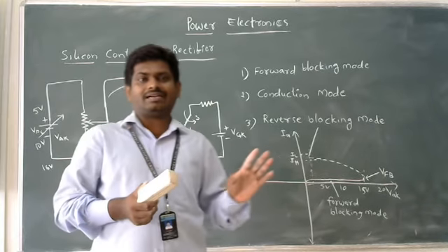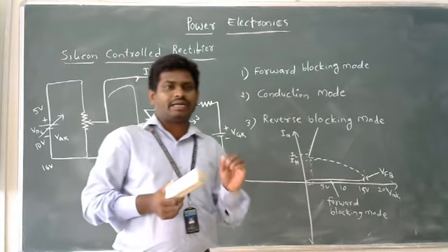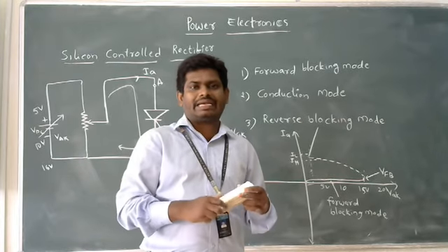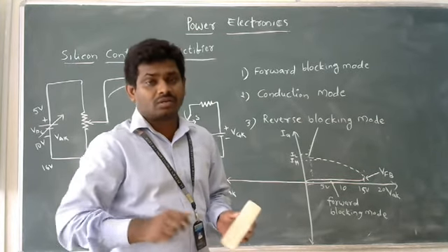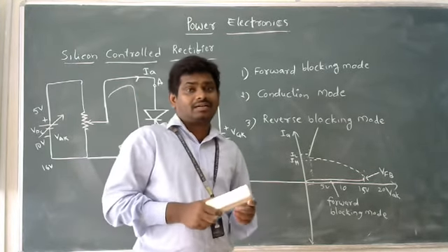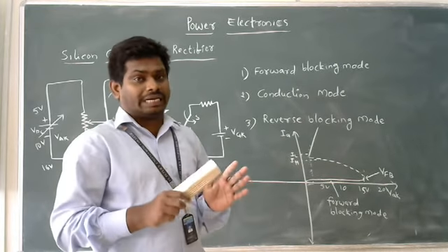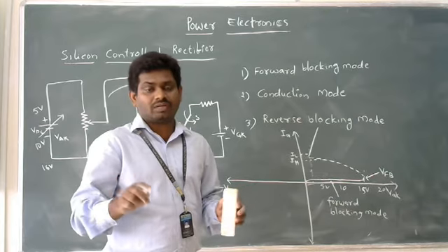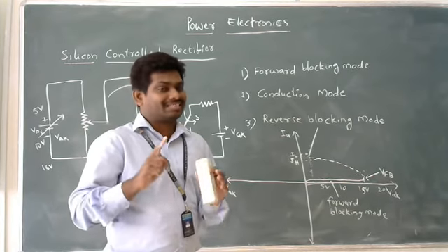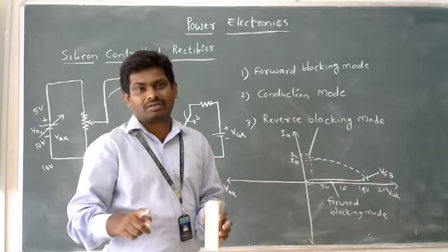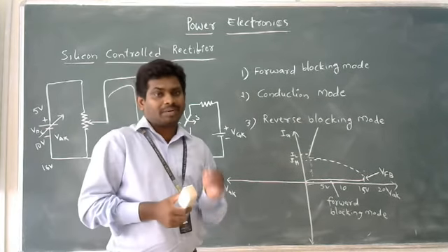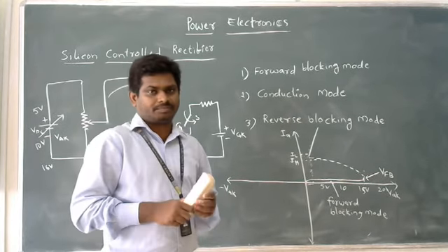It is very clear from the two statements. For holding current, we do not call any gate voltage or gate current values. But in case of latching current, a term called gate current comes into action. Even though the gate signal is removed, the SCR must be in the conducting state. For that, the minimum current is the latching current.